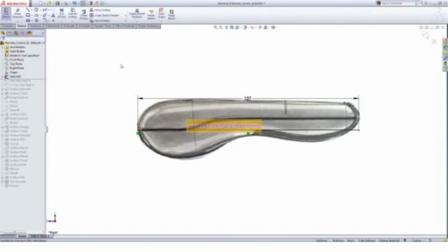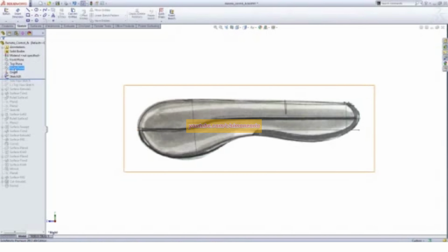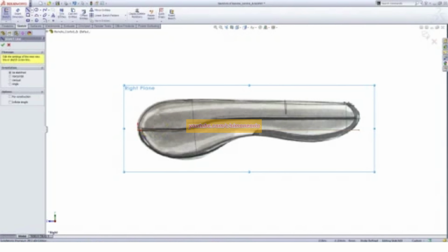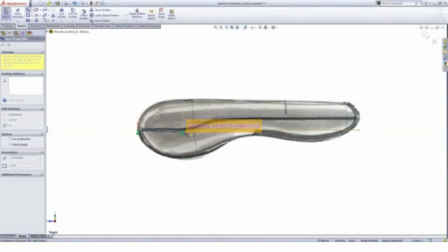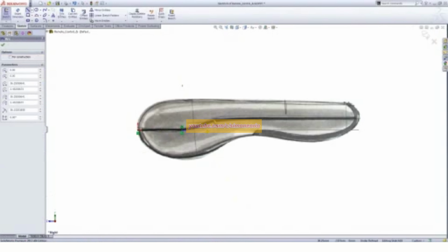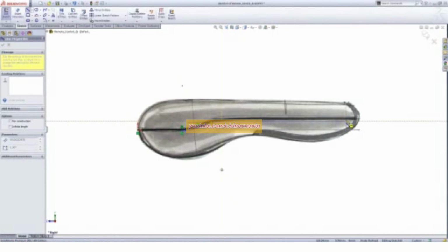Okay, the next step would then be to create some CAD geometry around this. An industrial designer that I met several years ago told me that he always starts from the edges. He designs from the parting line and the edges, and you can see that the artist here has illustrated the edges, especially if we look at the top view of that. So I can then very quickly start sketching here, maybe just pick out a couple of lines and arcs, and sketch out about where I want that parting line to go.